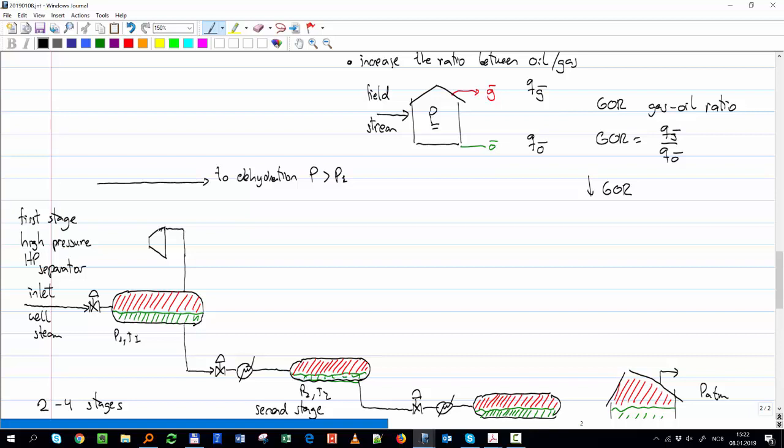But it's not so simple, okay? Why? Because the moment this gas flows into the pipe to go to the compressor, the pressure is going to reduce, is going to drop, okay? Because it's losing energy when it goes to that compressor. When it drops, you get oil out of this gas, okay? And you can get water, you can get liquids out of this gas. And compressor doesn't like liquid, okay, at all.